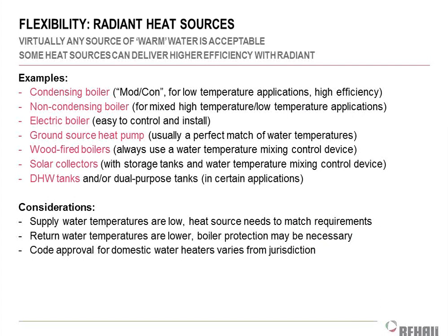Obviously, you can use solar panels on your roof to do your radiant floor, although it's not the best application because most of your solar energy is in the summer and most of your radiant needs are in the winter, so they don't really match up very well. But we do typically use solar systems around here for doing pool heating and stuff like that, because then the supply versus demand match up nicely. But you could do it for your radiant floor if you want to.